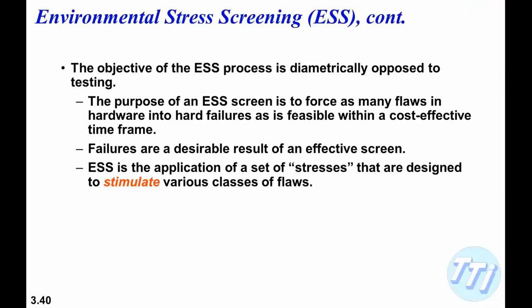The objective of the ESS screen is to force as many flaws in the hardware into hard failures as is feasible within a cost-effective time frame. Failures are a desirable result of an effective screen, and ESS is the application of a set of stresses that are designed to stimulate the various classes of flaws. They may or may not have anything to do with what's going on in the real environment.